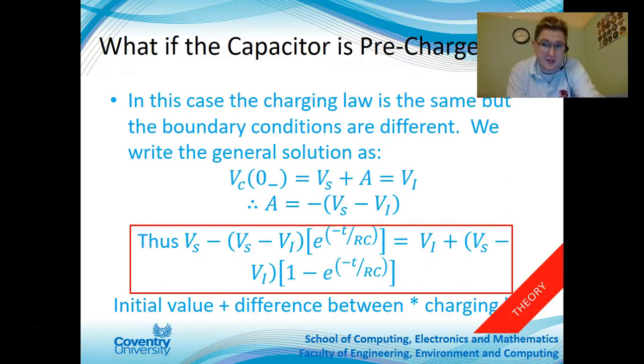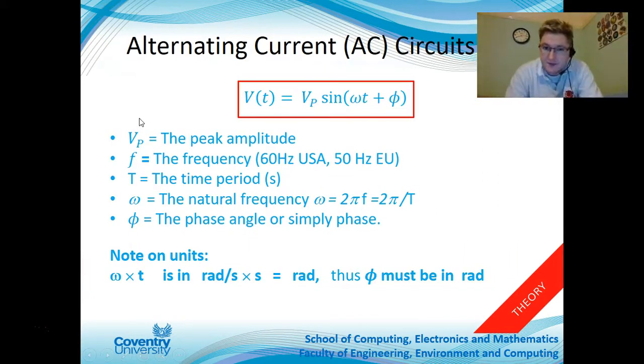Okay, I believe the second half of this question was about the instantaneous voltage in AC circuits. That material comes from lecture 9, so let's jump ahead to it. It comes from this slide here. If you've got v(t) = Vp sin(ωt + φ), you know what omega is, it's 2πf. You substitute the time that you want in for t, and you know what the peak is, so you can substitute that in, and you will find the value.